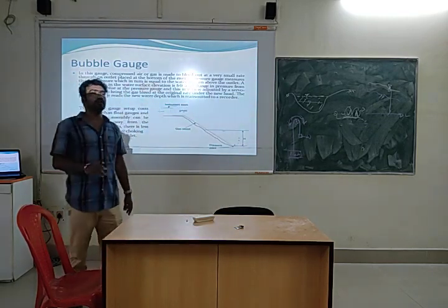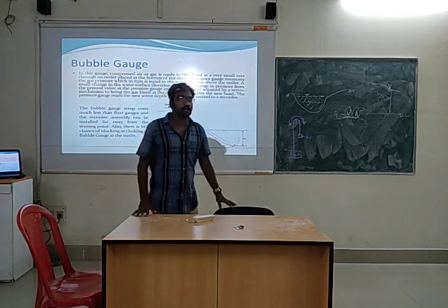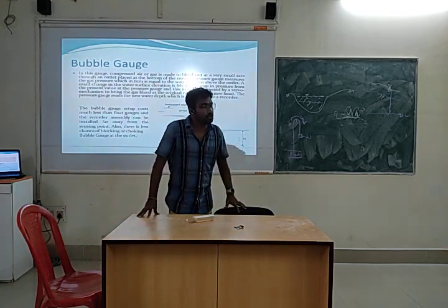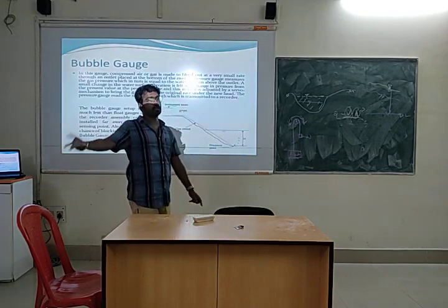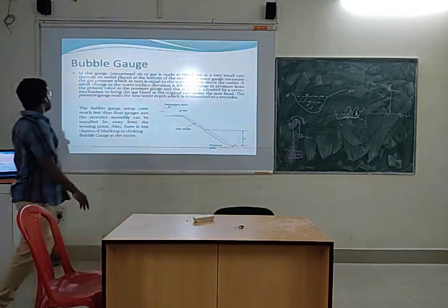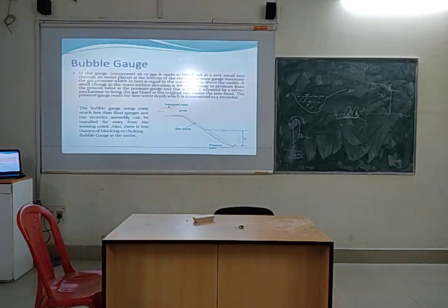If the weight of the column is increasing, that means the pressure exerted by the water will be increasing. If decreasing, then the pressure will be decreasing. Right? So a small change in the water surface elevation is felt as a change in pressure from the present value at the pressure gauge, right?